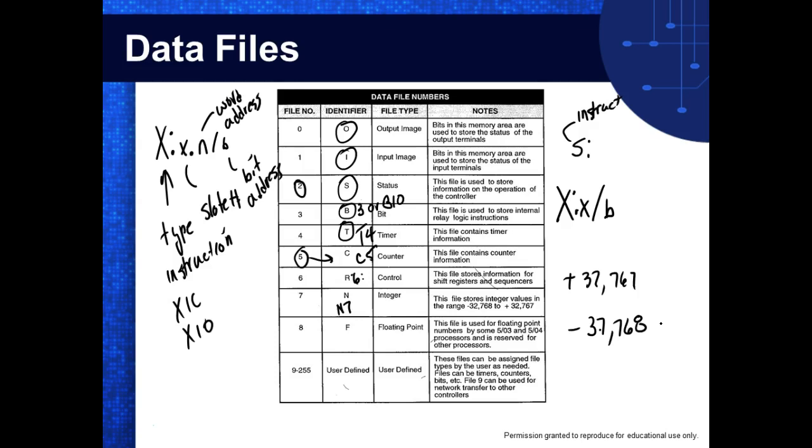So this is the range for our counters. If you got an up counter, the maximum that one counter can count up to would be what? 32,767, and then it would roll over. So we have another flag that we didn't mention because we didn't use it. We have an overflow flag that's available for our counters. An overflow flag would tell us that we exceeded what? 32,767, right?